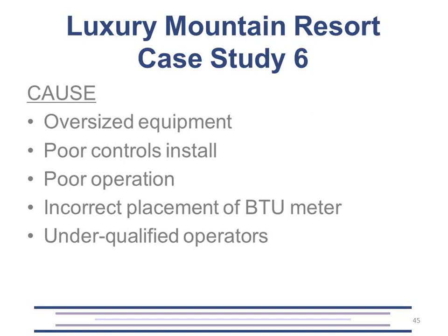Observations indicated that the designers oversized the chiller and the boilers. The chiller couldn't even stay on longer than its minimum on-time limit. It was having problems even during the hottest days of the summer. The equipment that was selected had very high efficiency ratings, and the system should have been able to run really well together, but the controls weren't installed well. And they didn't employ strategies that were actually necessary to achieve any of these energy savings and to operate this equipment as it should have been.